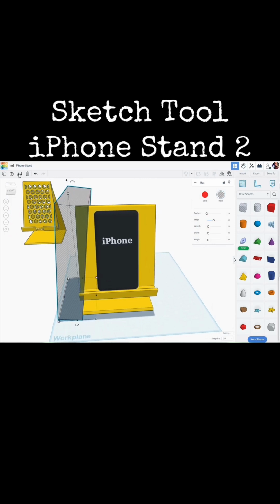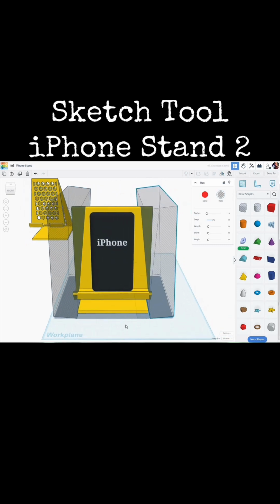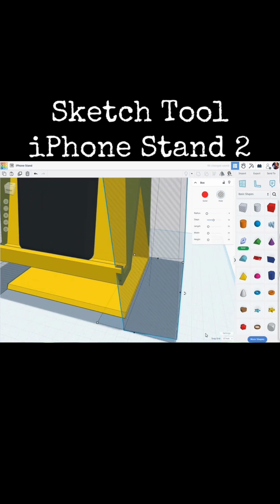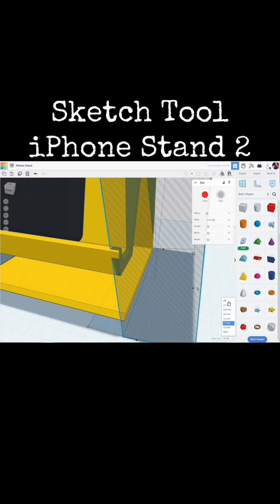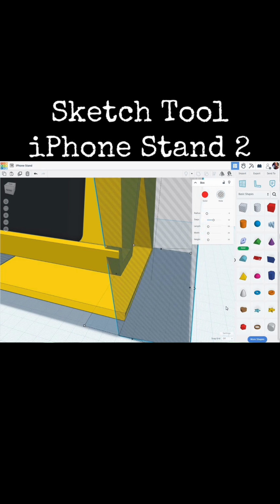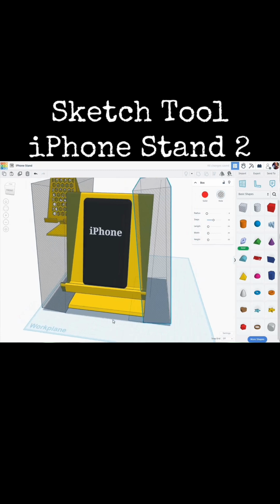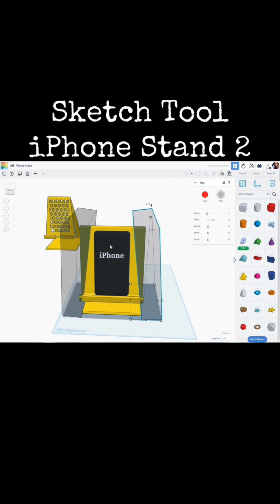Let's make a duplicate of that whole shape. I'm going to hit the mirror key. Let's mirror it this direction. Let's change our snap grid to 1 here. That'll move a little faster. Let's do the same thing. Let's zoom in a bit here. Change this to off. Holding the Shift key, let's move that over till it just cuts the bottom off. All right, so that'll be our basic shape.